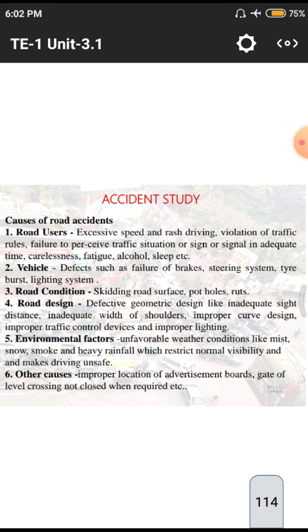Likewise, we have different lengths for different roads. For n number of lanes, we need to multiply n by 3.5. Similarly, we have to use these lengths and widths at particular positions. In case there is a turning, we automatically need to enlarge our roads to counteract accidents. Those come under road design.